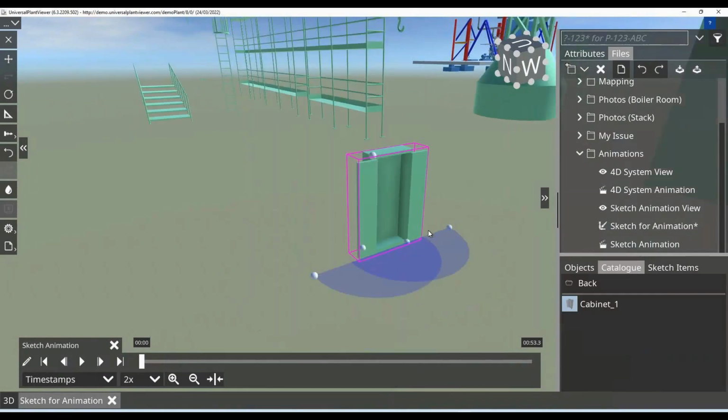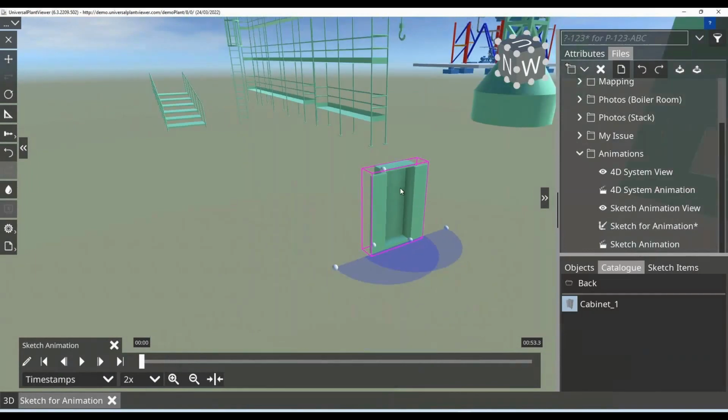So quite simple. It's just modifying 2 parameters in a 3D Symbol Designer symbol that are used to define the rotation angles of the doors. And that's it. And here we have a linear handle to resize the shape so we can make it bigger or smaller. So that's it regarding these handles in a 3D Symbol Designer.